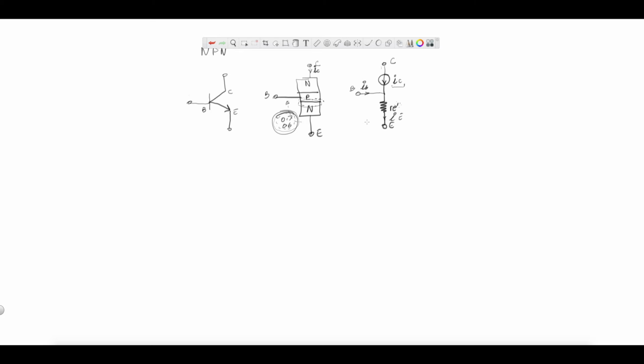If that's the case, then we would be interested in a few things. What is the impedance seen from this stage? So what is Zn seen this way? Let's think about this for a minute. Let's say we have IE going through RE. Well, that means we have a voltage from here to here. This time I'm going to write it little VBE in AC.